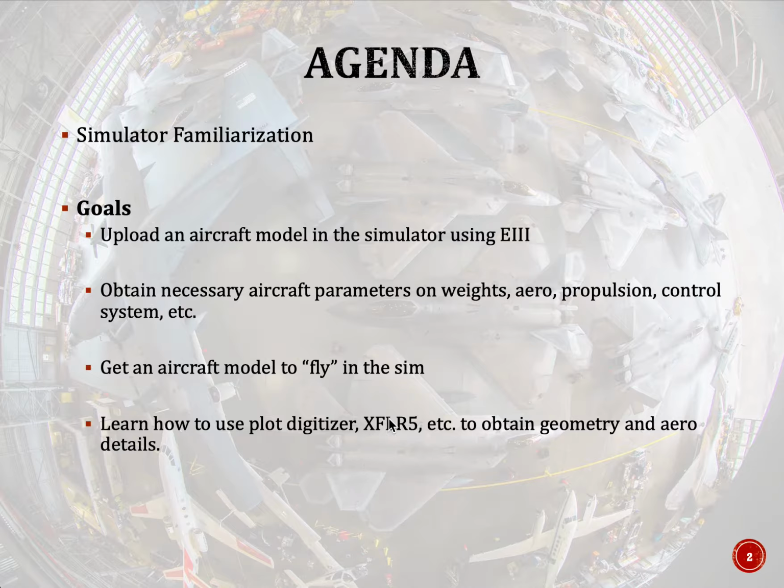And then with XFLR5, if you find out what type of airfoil it is using, then you can create the CL, CD, CM for that airfoil at a particular Reynolds number, and you can input that into the simulator model as well. All right. So that's basically the goals.